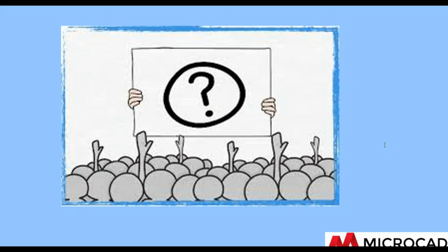And there was a question about bringing in PDFs. There's a couple of things that are built into BIM 360. The first is if you have a multi-page PDF, then you can set up in BIM 360 the ability to find the sheet name and the sheet number. And when that entire multi-sheet PDF is loaded, BIM 360 will break out each individual sheet for separate access. So you would see on your browser tree all of the sheets in a PDF.